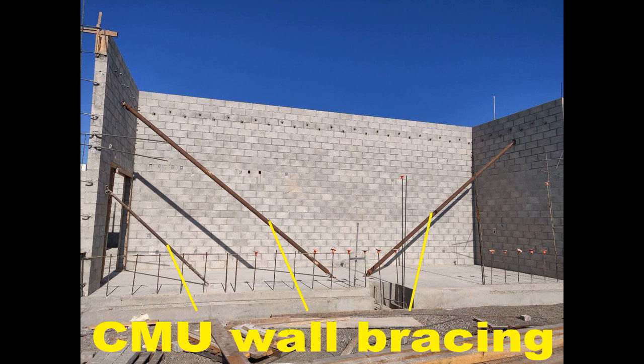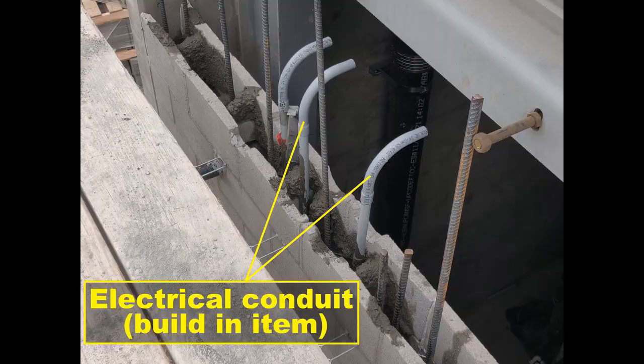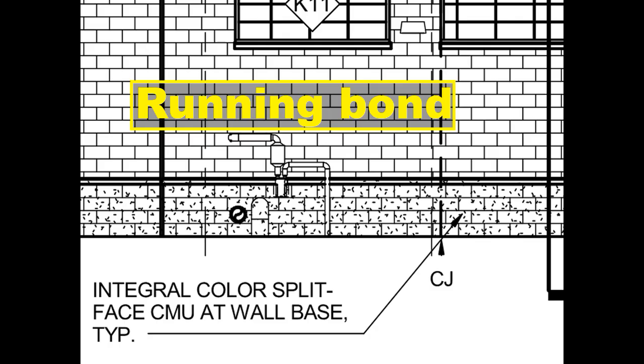Bracing. Provide bracing and scaffolding necessary for masonry work. Design bracing to resist wind pressure as required by OSHA and local codes and submit bracing calculations. Do not remove bracing in less than 10 days. Coordinate masonry work with the work of other trades to accommodate built-in items and to avoid cutting and patching. Lay masonry units in running or stack bond pattern as indicated in drawings.